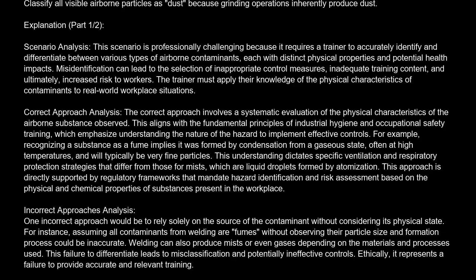The correct answer is C. Classify all visible airborne particles as dust because grinding operations inherently produce dust. Explanation. Scenario analysis. This scenario is professionally challenging because it requires a trainer to accurately identify and differentiate between various types of airborne contaminants, each with distinct physical properties and potential health impacts. Misidentification can lead to the selection of inappropriate control measures, inadequate training content, and ultimately, increased risk to workers. The trainer must apply their knowledge of the physical characteristics of contaminants to real-world workplace situations.